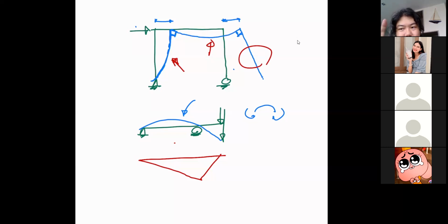If you don't say anything, I will have to assume that we all draw our bending moment diagram on the compression side. If you draw it on the wrong side, I would have to assume that perhaps you don't know what you're doing. But it will be good if we can indicate it. It's always good if you can provide enough information for yourself and others, of course.